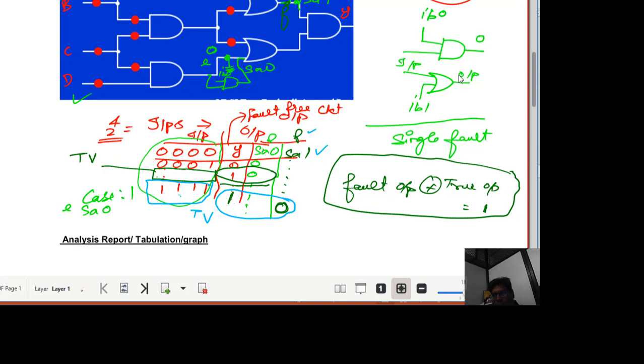These are the two major stuck-at faults. You could inject that stuck-at fault by incorporating an AND gate or OR gate. In reality, it is not true. What we are trying to mimic is the behavior of the manufacturing defect that happens in our circuit. True, that's it.